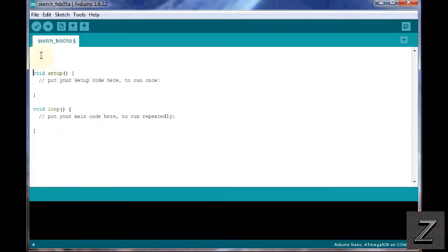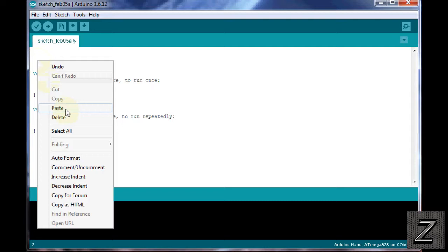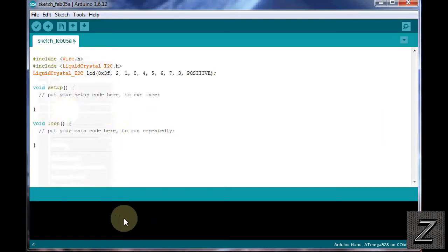So first we are going to include our libraries, and I just simply have a screen opened up on the side here instead of typing all this in. We're including the Wire.h, and that's for the I2C, and then we're including the LiquidCrystal I2C library. And then we're defining the address for the LCD screen because we're using I2C. Like I said, I have a video, and there will be a link to that on the website, on how to find your address and get everything set up. So just check that out if you've never used the LCD screen with your Arduino before.